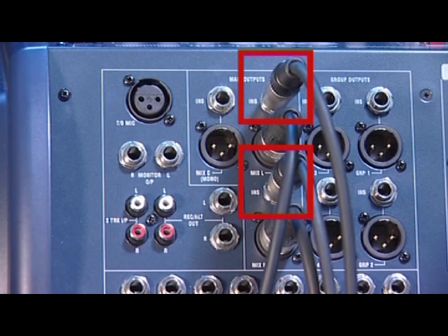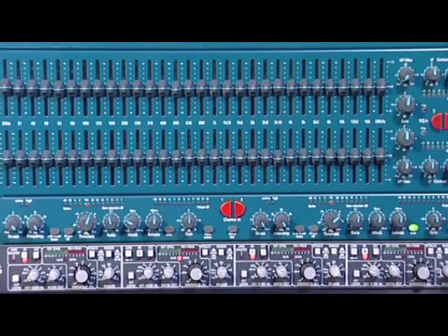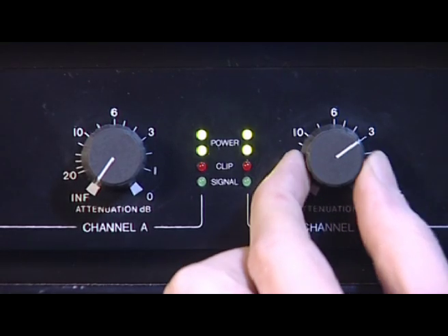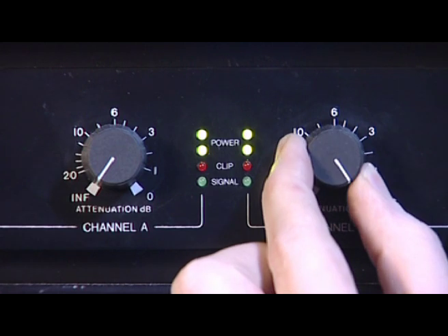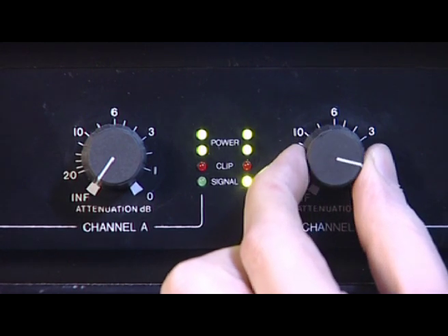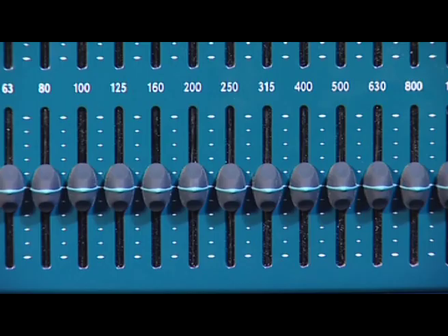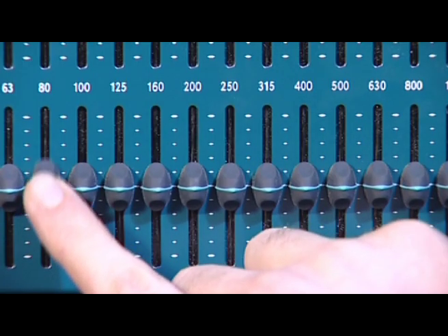Set all the graphic equalizer's controls to 0, which means that they'll be in the straight line centered on 0. Turn up the amplifier volume until you can just hear the sound start to ring. Turn back the volume slightly so that the ringing doesn't turn into feedback. Starting from the left, adjust the first graphic EQ control to maximum.